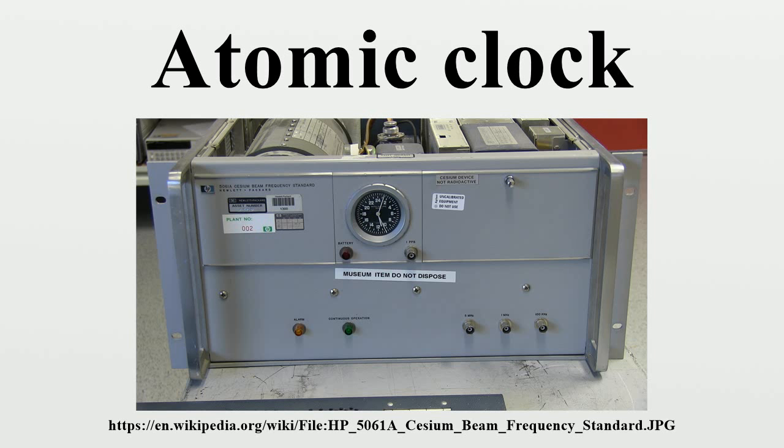Active maser standard. The active maser standard is a development from the atomic beam standard in which the observation time was incremented by using a bounce box. By controlling the beam intensity, spontaneous emission will provide sufficient energy to provide a continuous oscillation, which is being tapped and used as a reference for a flywheel oscillator.